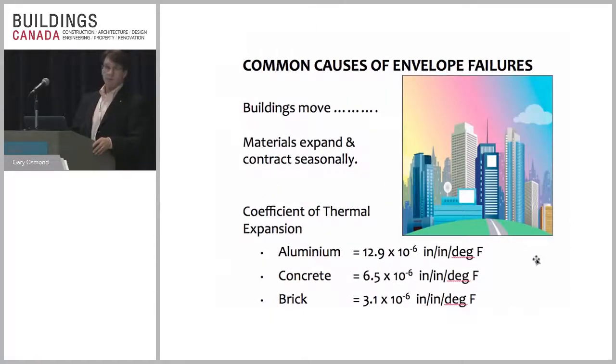Buildings move. Get over it. The way we build, again, thinking of all the people involved, because it is stick framing throughout the whole process through a myriad of weather conditions, buildings are going to change dynamically throughout the seasons. Materials expand and contract, and then we have this thing called the coefficient of thermal expansion and contraction. Seasonally, things move. I have aluminum shown here, and it's important to understand that this dimension here is the movement per inch of length per degree change.